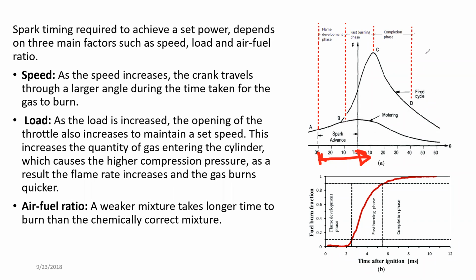So even though the engine speed increases, the combustion time is going to be the same. So in order to maintain this point C at the same level, the engine actually has to bring the spark ignition point a bit earlier from the TDC point.